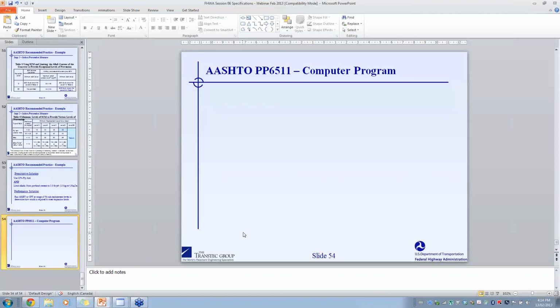And don't forget, that is for the most extreme possibility, where you're using the most highly reactive aggregate known to man, building a major structure, and you're going to throw salt on it. You may well decide that 35% isn't acceptable because of other considerations like the limit on salt scaling, and then the option is, you're going to have to use a less reactive aggregate to find yourself in a lower category.